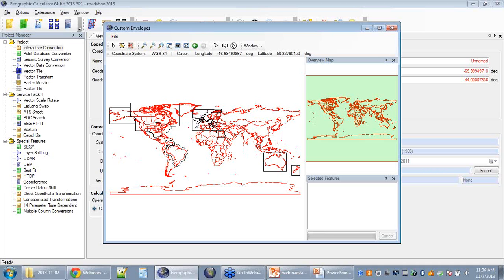However, if you are, say, working in another tool, if you're working over in Global Mapper, and you actually want to get a little more complicated with some of those envelopes, you can load in envelopes via a saved vector file. Pretty much whatever kind of vector file you want. There are about 20 some odd vector formats that are supported here in the calculator. Simple things like shape files or CAD drawings, KML, GML, a number of types of vector data.